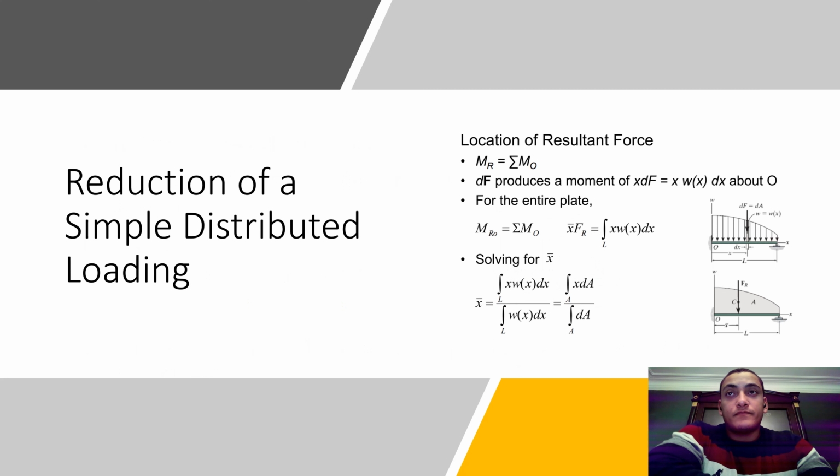Reduction of a simple distributed loading. Location of resultant force. dF produces a moment of x dF equal to x w(x) dx about point O for the entire plate, as you can see in the example I provided for you and the equations that are used.